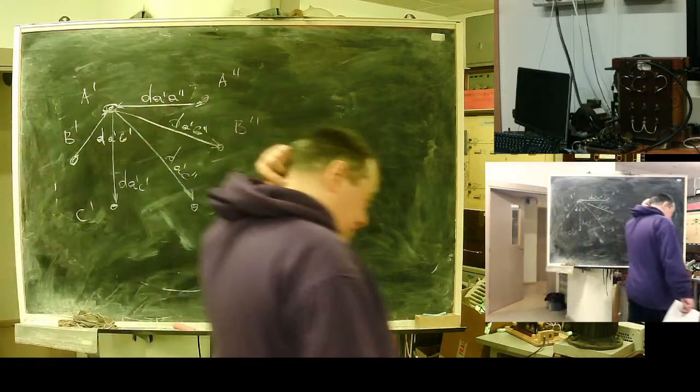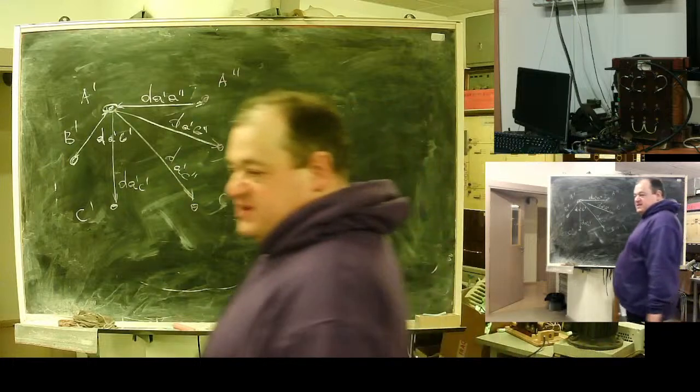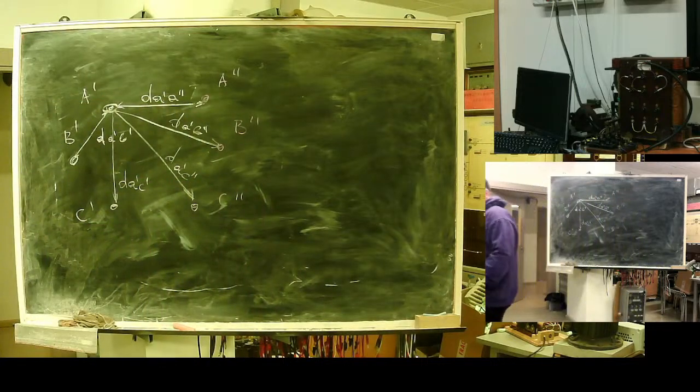In general, if we agree to live with the error, we can assume a full transposition cycle for both lines. This means for direct and negative sequence, mutual influence is negligible.